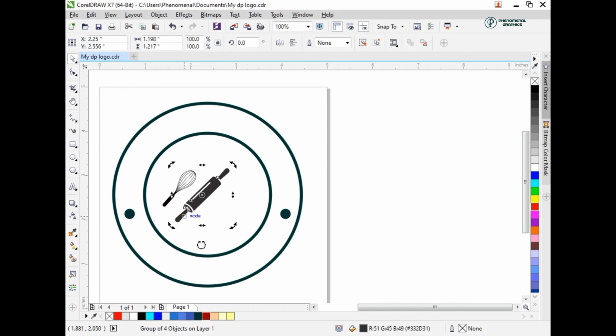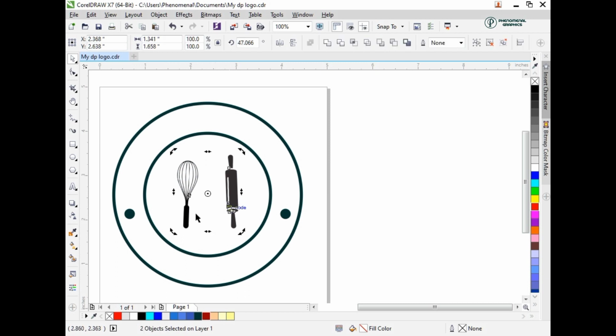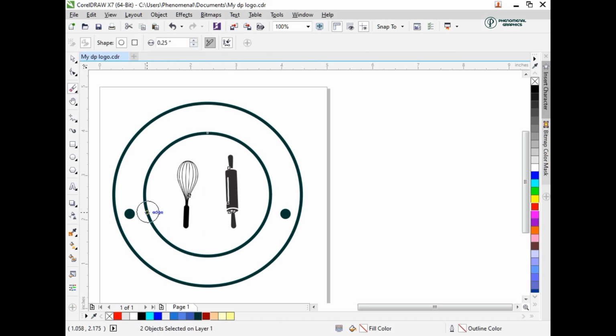So right now I can click on this, rotate it, make it straight, control Z, and then I can drag it to the side. Do the same thing for this, resize it a little bit, then rotate it. I can select the two, hold your control key, press B on my keyboard, then group it up. But after grouping, select this, then press C and E on my keyboard, C and E. So that's okay.